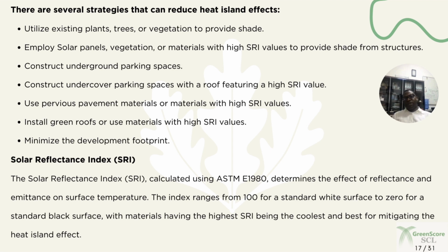Also, there are innovations around pervious pavement materials or materials with high SRI values, vegetated roofs, or use of materials with high SRI values, and of course, minimizing development footprint. Now, we talked about SRI, and you need to be sure that the reference standard by which it is calculated is ASTM E1980. ASTM E1980. That you can see what the solar reflectance index is all about.